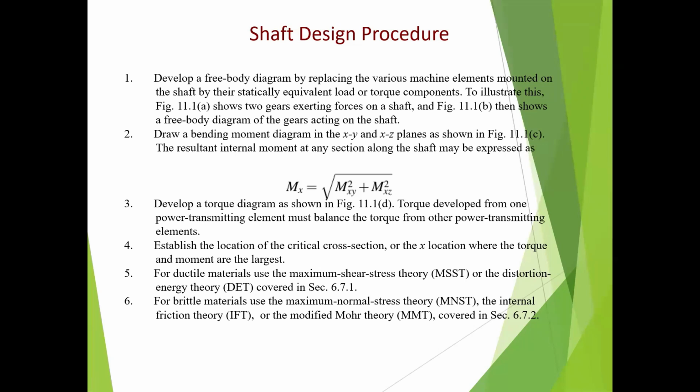And in order for this element to be in a state of equilibrium, we must have the 3 force balance equations along with 3 moment balance equations. So develop a free body diagram by replacing the various machine elements mounted on the shaft by their statically equivalent load or torque components. This is what I just told you.